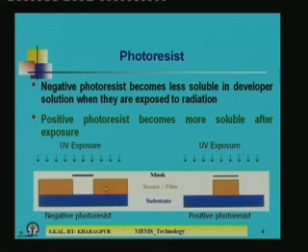Here on the left side of the picture, the red portion will be exposed with ultraviolet light and hardened, and the unexposed portion will remain soft, as a result of which after developing, this portion of photoresist will be removed and we will get windows with a black region on top of this particular window.